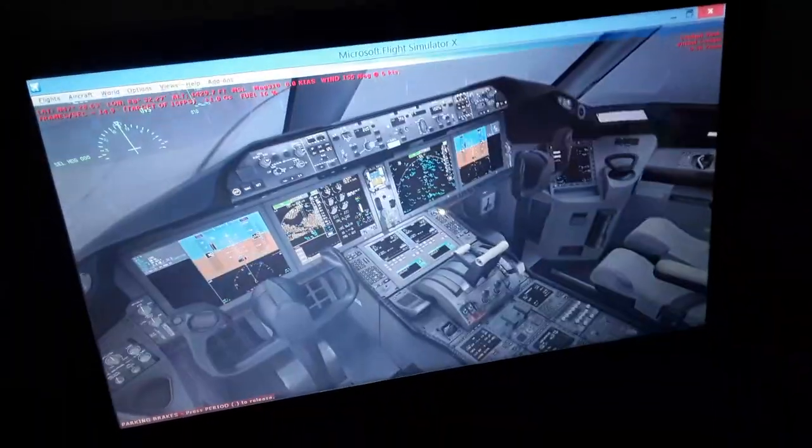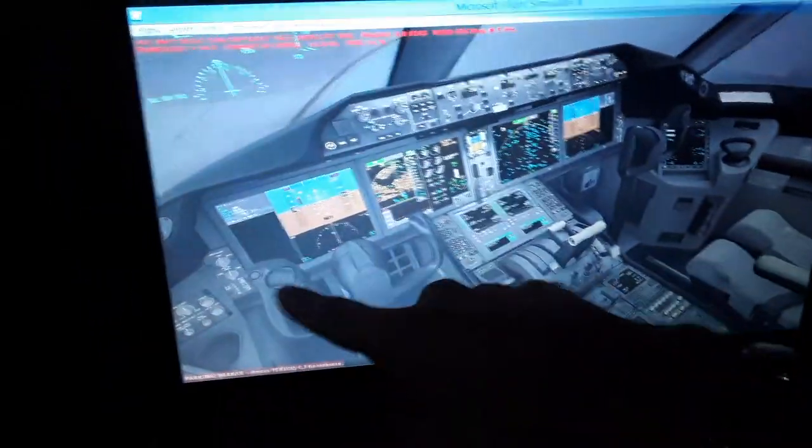We have also, this is a fly-by-wire aircraft, so this is the manual trim channel. It has flight control computers, it's a fly-by-wire aircraft. It has also the automatic trim, the auto trim function of the Boeing 787. So when you use the autopilot flight director system panel, the auto throttle, the flight management computer with the LNAV and the VNAV modes, you will see later. We have the auto trim function that the aircraft can trim itself using its flight control computers in flight. So you don't need to trim it, maybe a little bit. So you have also this function.